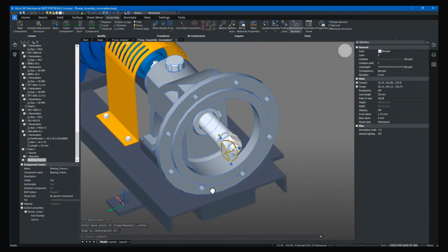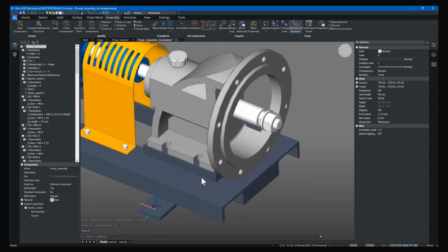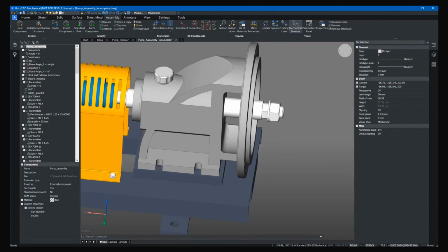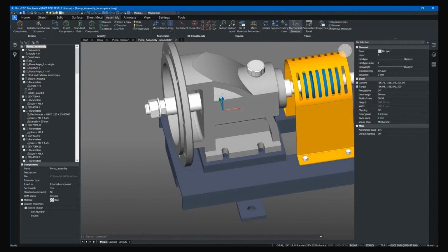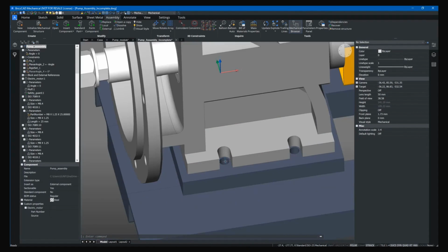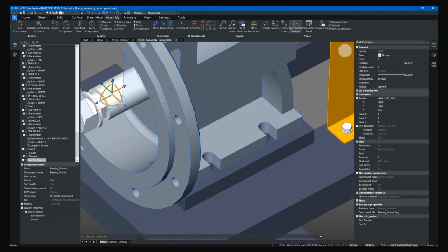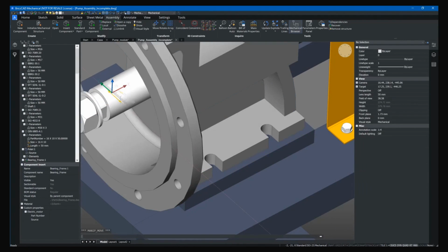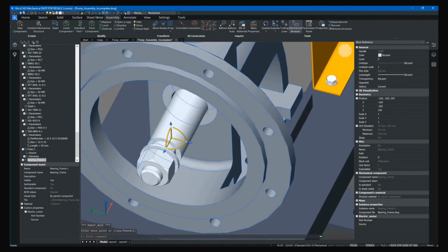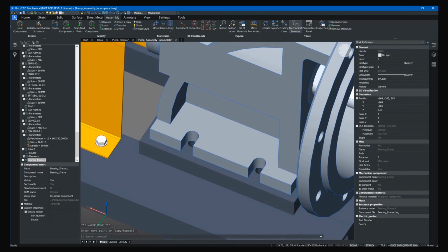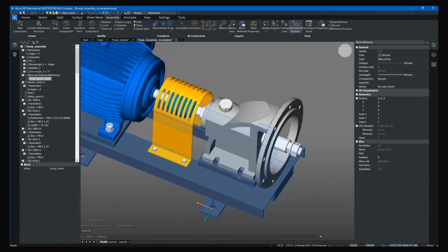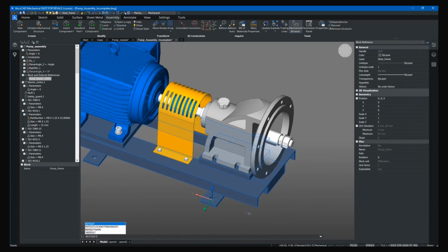So I positioned it correctly with the holes on the other side, but we can see here it didn't fit. While here it does fit, meaning the hole pattern is not correct according to the part we have. So I now placed the actual part in the middle, and we can actually now go ahead and edit the bottom plate in place.